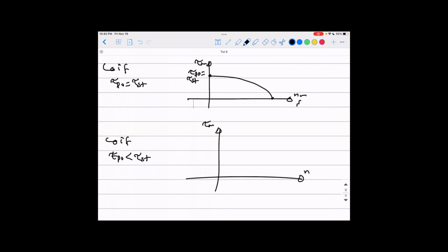Can this happen? Yes, it can, sometimes. If you look at the standardization page, which is a mandatory self-study page from the online materials I told you about in previous lectures, you'll see motors with torque-speed curves that look like this. This is the pullout torque and this is your starting torque, and the starting torque is higher than the pullout torque.